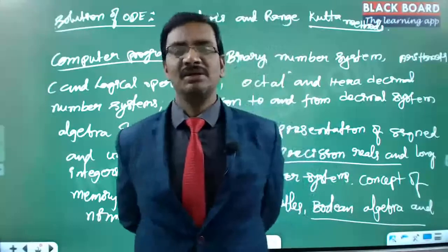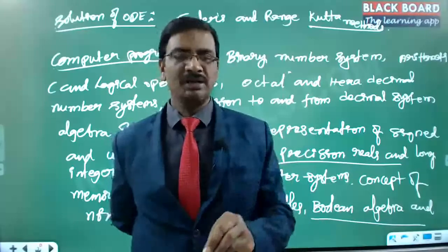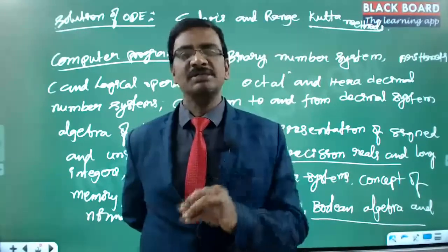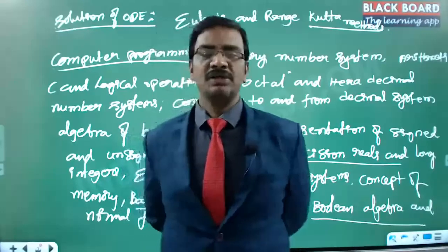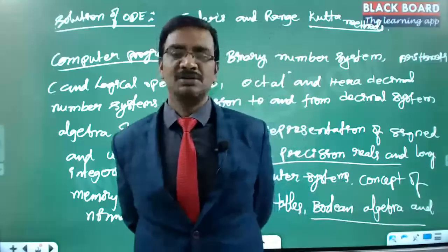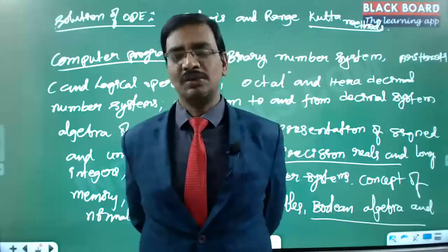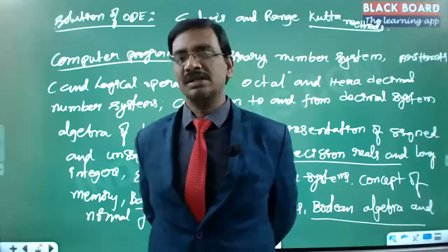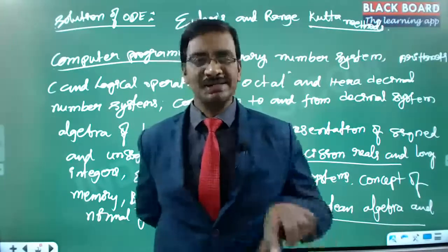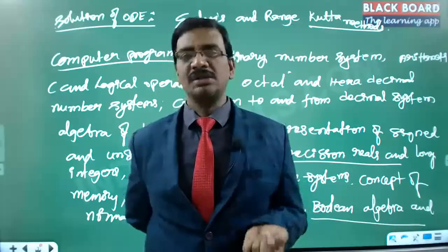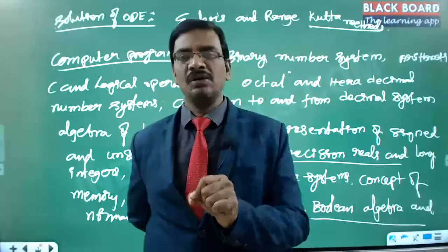In exactly the similar manner, there is one more algebra we are bringing in, to deal with binary numbers. That algebra is the Boolean algebra, right? In the decimal number system, 1 plus 1 is 2, right? 1 plus 1 is equal to 2. But in Boolean algebra, 1 plus 1 is treated as 1 itself. The plus is treated as an OR, and 1 is treated as true, and the other 1 is treated as true. So true or true, the result is true.